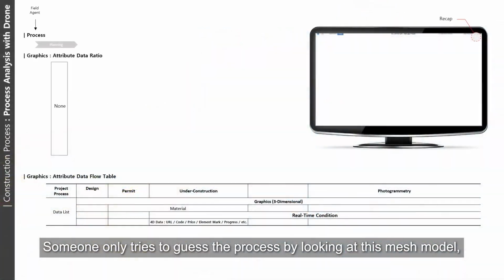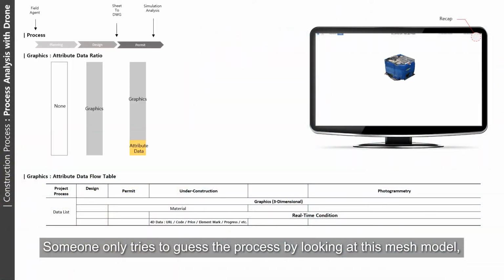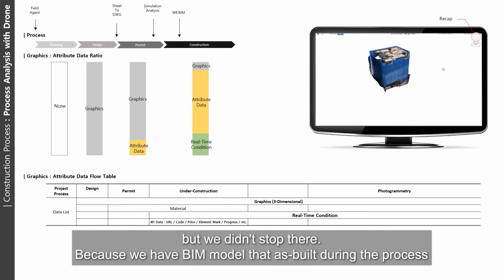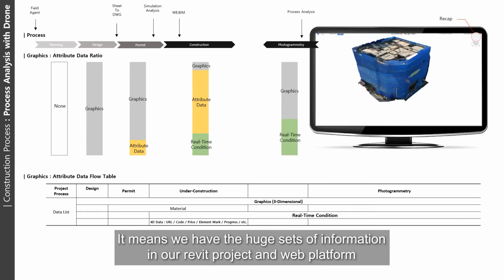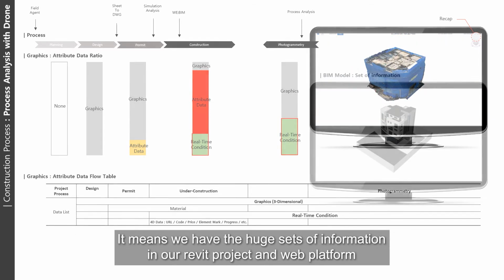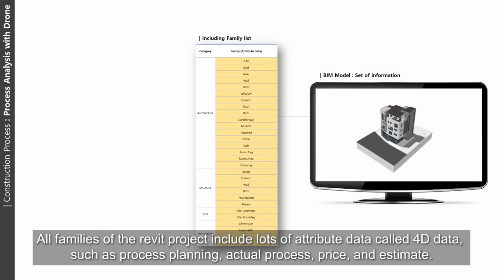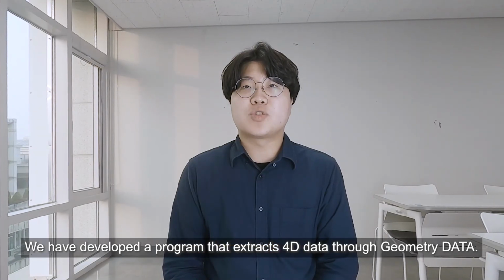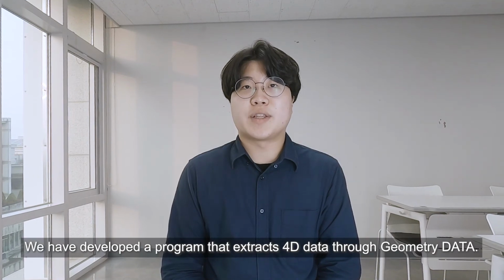Someone might only try to guess the process by looking at this mesh model, but we didn't stop there. Because we have a BIM model that is built during the process, it means we have huge sets of information in our Revit project and web platform. All the families of the Revit project include lots of attribute data called 4D data, such as process planning, actual planning, price, and estimate. We have developed a program that extracts 4D data through geometry data.